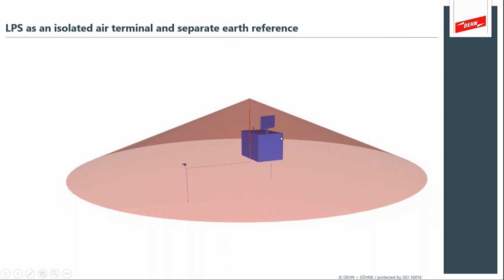And then at the structure itself, the blue, it might look like a blue shelter, maybe a metal ISO container that has its own earthing rod. And with suitable distance through the soil, you can prevent that ground potential rise from polluting your ground system of that shelter.